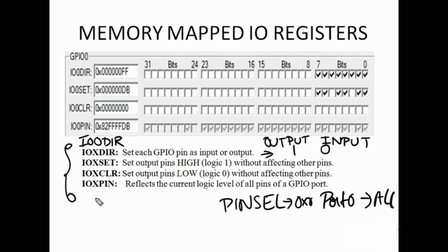Let me consider this is my microcontroller. In our case, it is nothing but LPC2148. This is some peripheral device. It doesn't matter what exact device it is. You know that this microcontroller should be connected to the peripheral through some pins, correct? So if you want to send some signal to the peripheral from the microcontroller, you will need output pins.